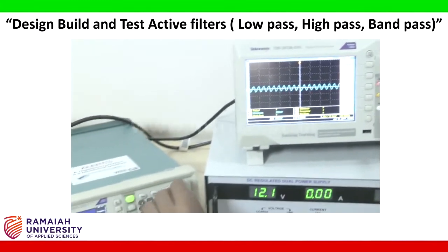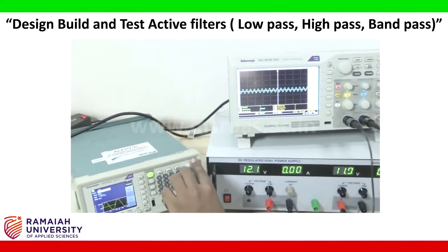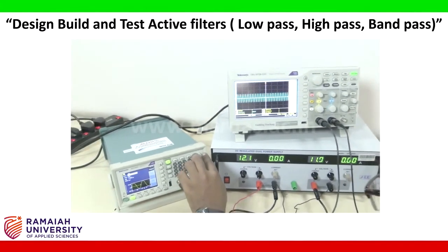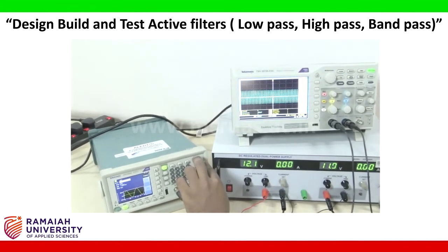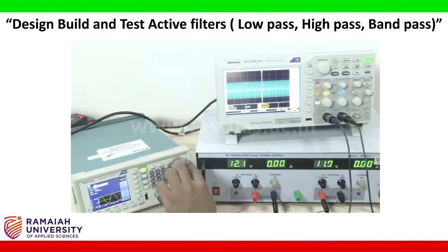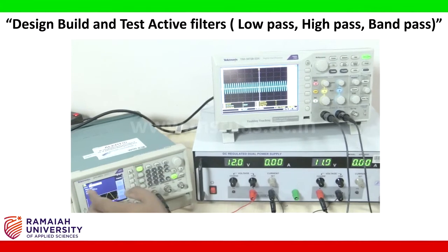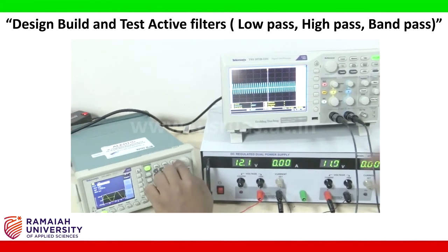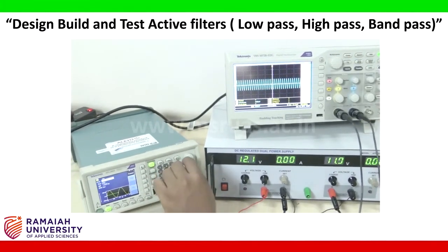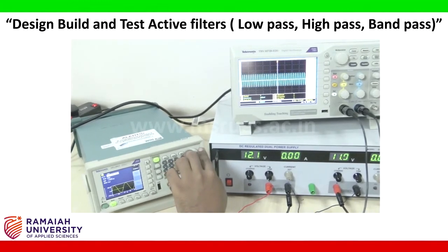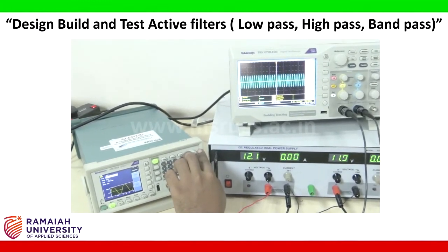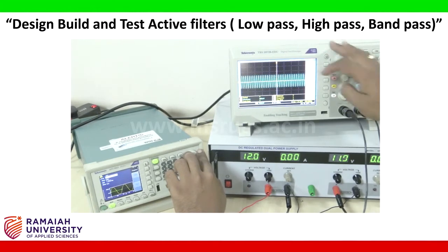Further, I increase this to 1 kilohertz directly, until then it will give an incremented version of the output in the amplitude, you see. So for example, at 700 hertz, the output will be 2 volt peak to peak. If we increment to 800 hertz, it will give some 2.2 volt peak to peak.